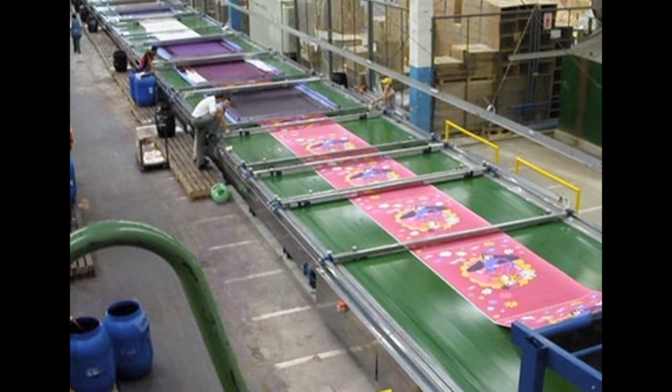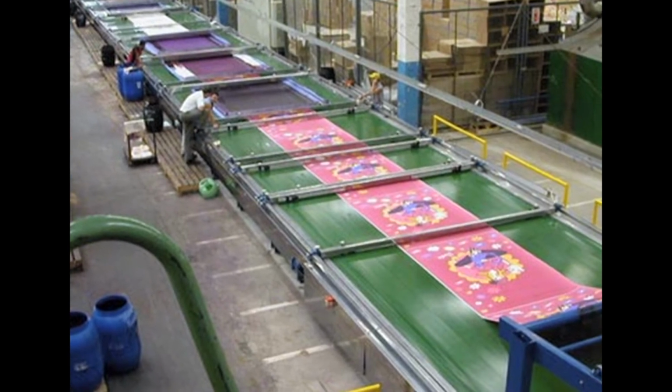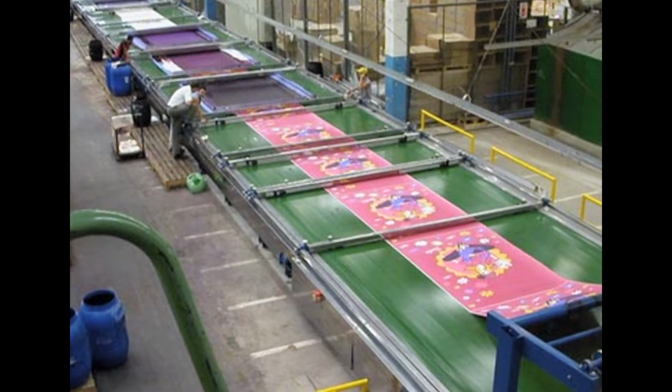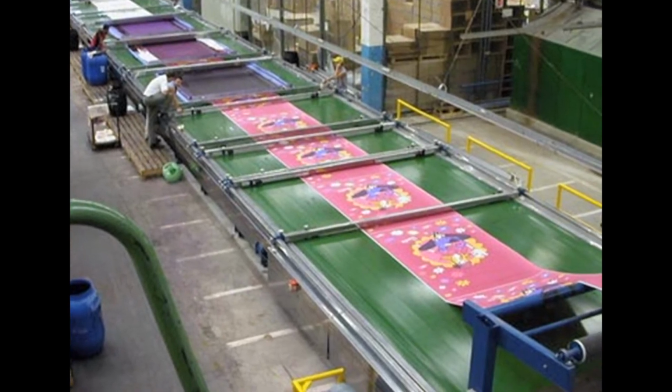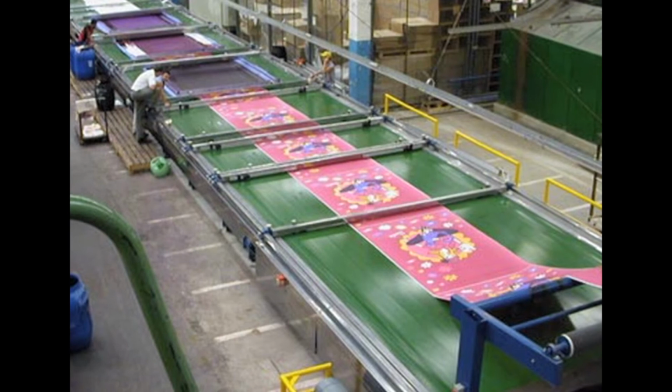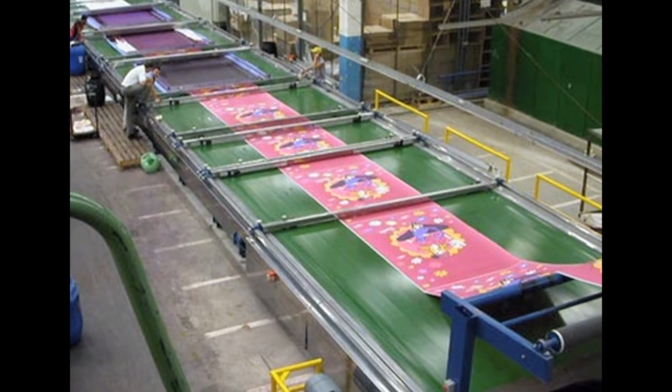In this method, the back of the fabric to be printed is coated with an adhesive which causes it to adhere to the backing on a rubber conveyor belt that serves as a tabletop for printing. A series of flat screens, one for each color, are set in frames with automatically operated squeegees and are placed above the belt. After printing, the cloth is continuously fed into an oven to be dried.